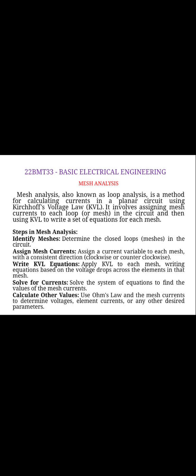Sometimes in the given problem the current direction is also mentioned, otherwise we can assign the mesh currents. Next step, write the Kirchhoff's voltage law equation, the KVL equation, for each mesh present in the given problem. Then solve the currents and calculate the values.